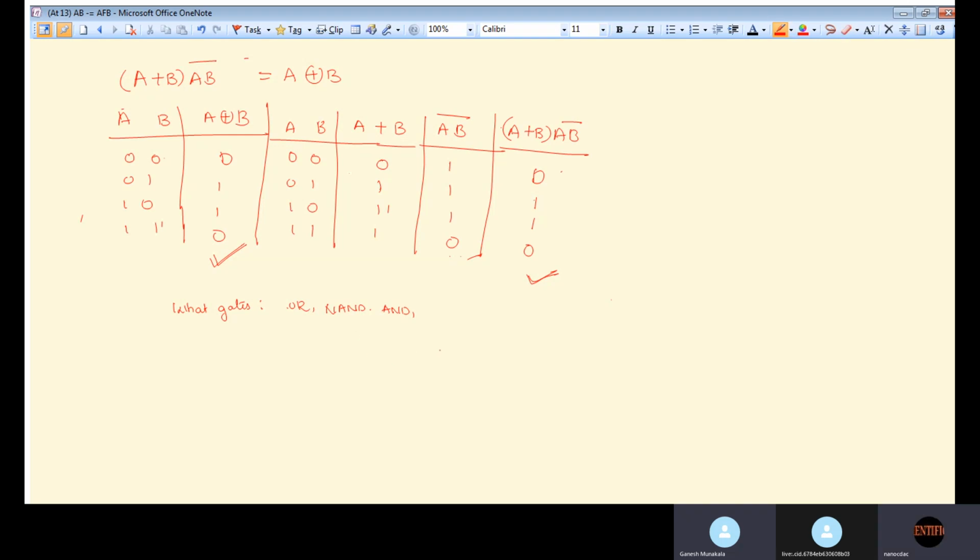Okay, we will start with A plus B ఉంది కదా. So here we are getting A plus B. A plus B వచ్చి మళ్ళీ తర్వాత AB bar కదా. సో ఇప్పుడు NAND గేట్ తీసుకోవచ్చు. AB ఇక్కడ వచ్చి AB bar, లేదంటే one NAND gate, one inverter also you can take. So A plus B into finally you are feeding one NAND gate.